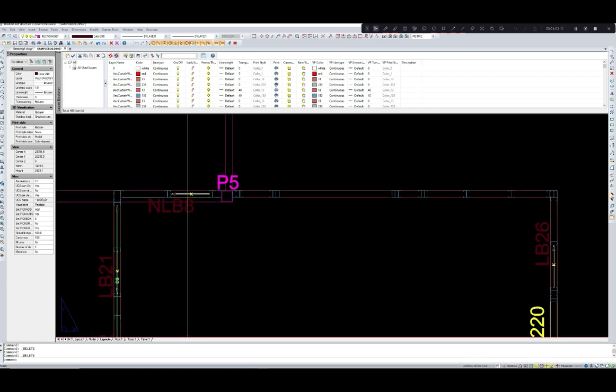Now we shall introduce a big opening. A window for window opening, user defined window opening. UW is the command. UW. Let us take its head location. Head H and enter. Then 2500 is the head height. Then let us take opening height as 2000 mm and the opening width is 2750 mm.